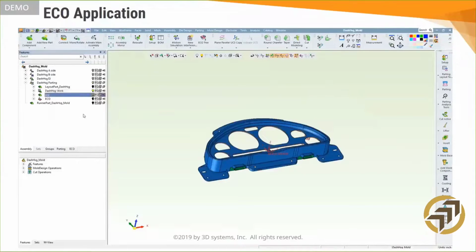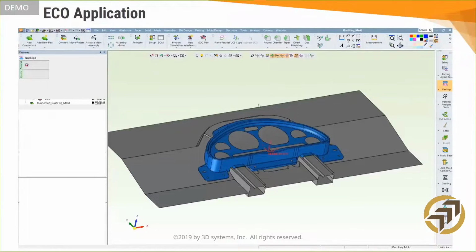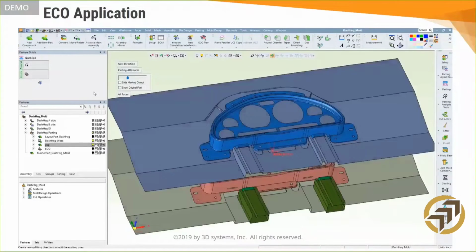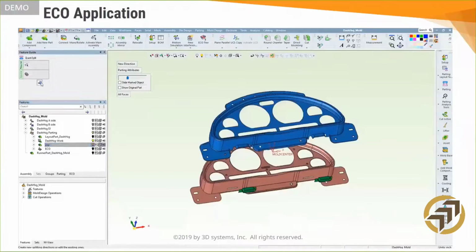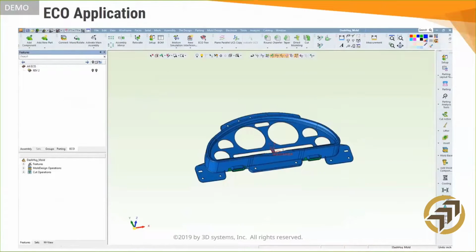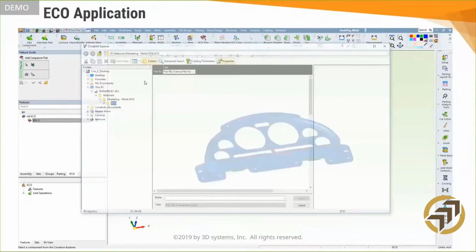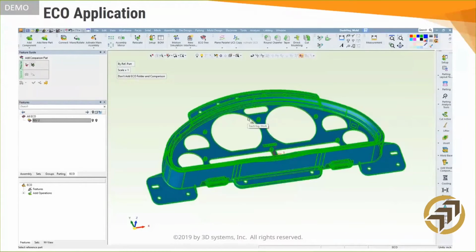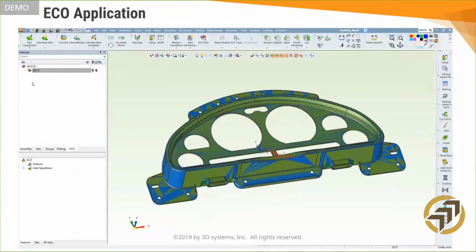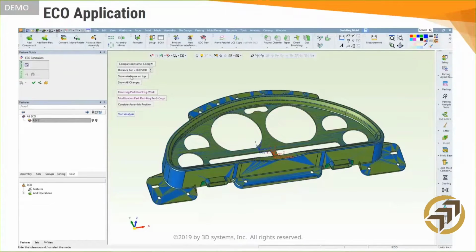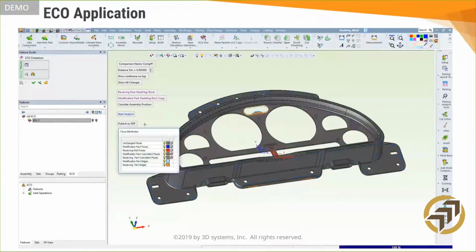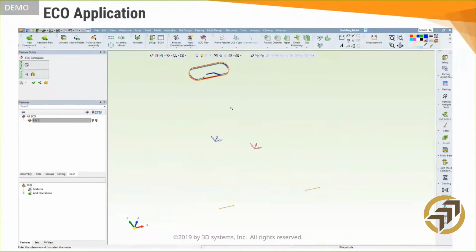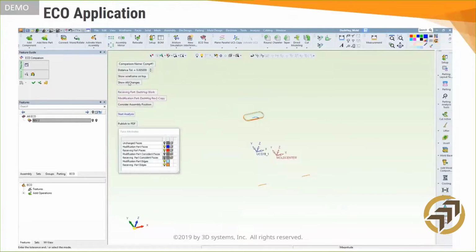In the mold making business, being prepared for engineering changes is a must. Because the Cimatron solution follows a top-down approach from the part to design to NC and documentation, there's a fully associative pathway for the new revision to follow, and it provides the ability to update all areas of the process on the fly. The first step, of course, is to simply find and verify the changes in the new revision, and this is done via a real mathematical comparison of the new data to the old. The results of that analysis are grouped and color-coded on the screen.